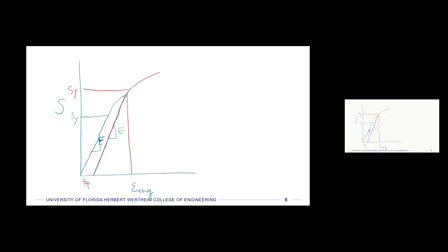So this permanent strain or plastic strain is going to be the first little region right there at the beginning of the plot. So I've written epsilon p right there. And then when we load it a second time, we actually are inducing a second round of elastic strain, so I'll have epsilon little e for elastic. And if I keep pulling on it, it's going to yield again. We can do this multiple times until we get too close to the ultimate strength, and then we start to lose this effect.